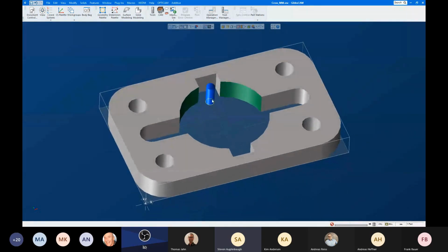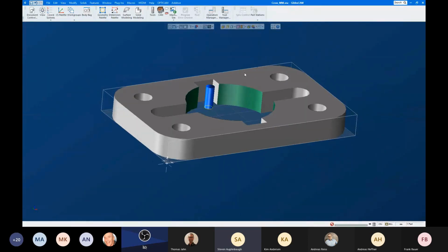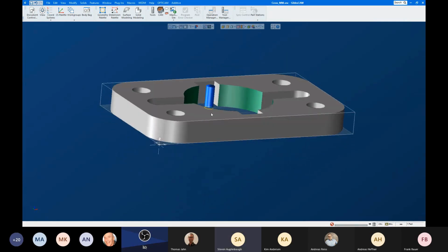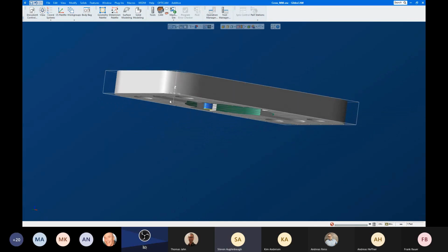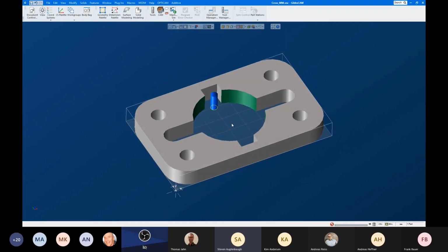Basically the way it works is it looks at the solid, it finds the height of the solid, and it creates the correct size cylinder. So really simple stuff, but basically that's what it does. And if you haven't noticed by now, everything is plus Z, okay? Because in EDM, the table is 0 and we work above the table. It's not like milling, where we're going to mill below. Everything is above. So that's why it always goes one direction. It won't go any other way.